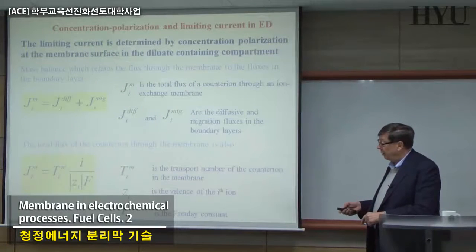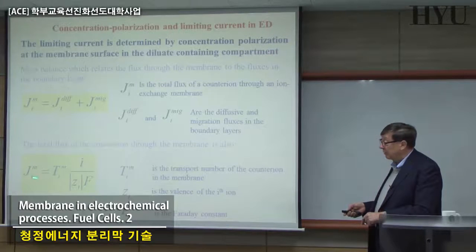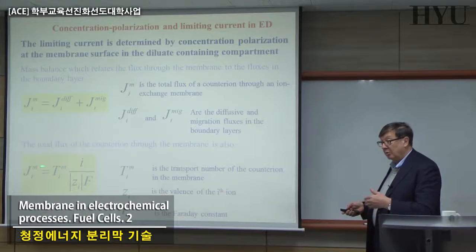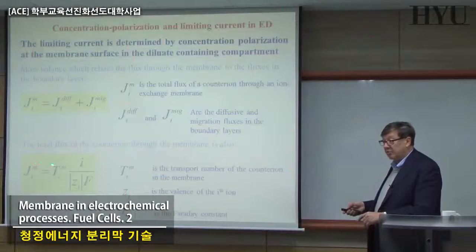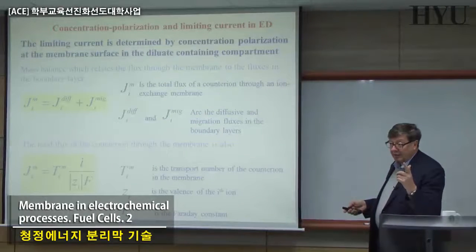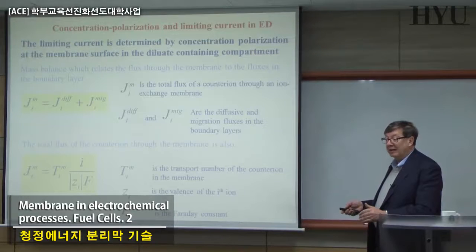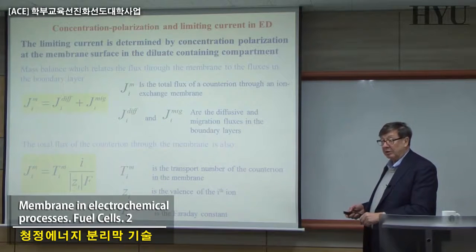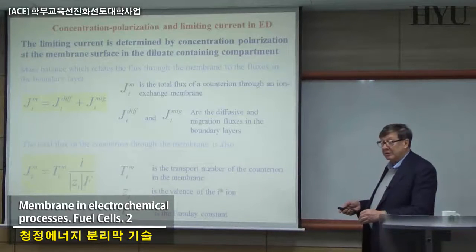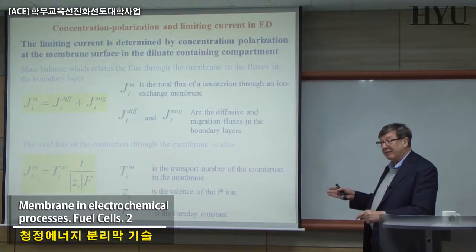Particularly in the membranes, we have to remember that the transport number, that means the amount of current transported by one ion, in this specific case the proton, is basically covering 100% of the current going across, if the membrane is perm-selective, as we are looking at in this case. Normally in the solution, the current is related to the transfer of ions, positive and negative.